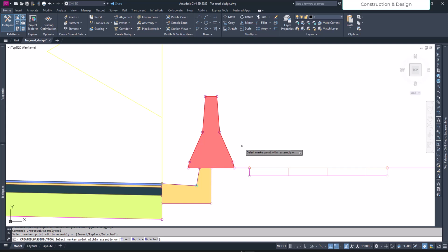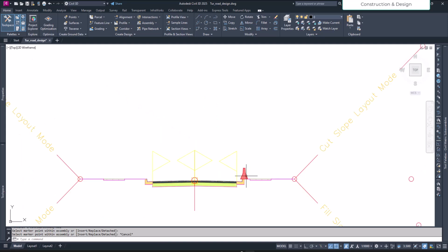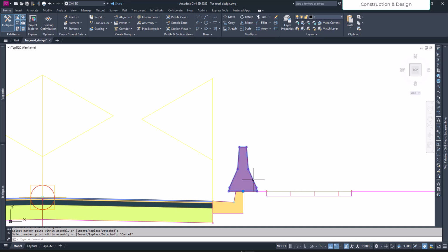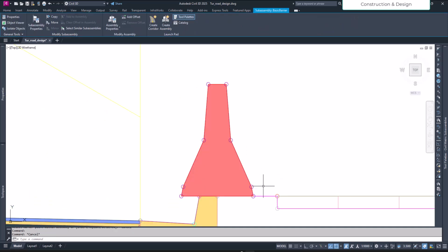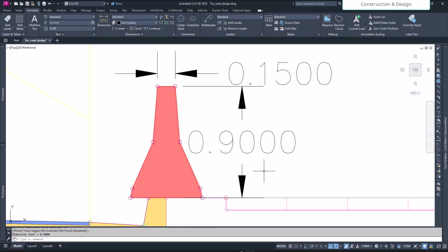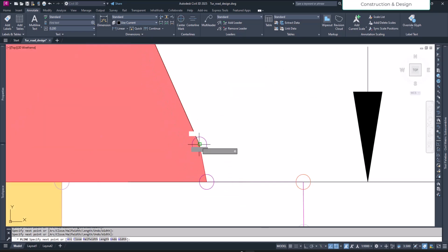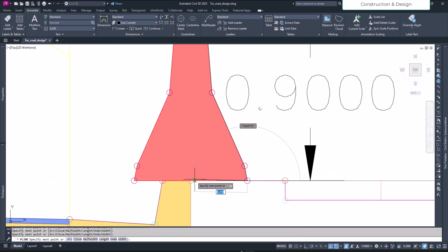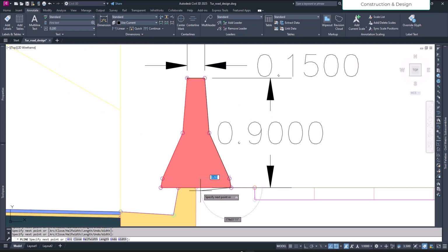Let's use this as the dimensions and create another polyline. We can actually trace on this as a polyline. Enter the polyline command, and then from the top let's say one, and then let's click here, click, click. Let's first trace all of this and then later we can modify it. And now to close it I will hit C and enter.